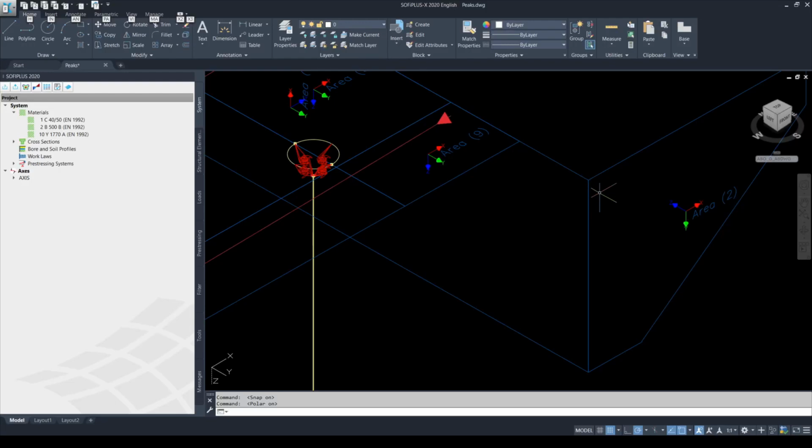I will just simply create a new material whose E modulus is going to be set to a quite small value, and I'm going to create an attribute area over the part of the wing wall that is failing in the design. In the properties of the attribute area, I'm going to set the new material with the small E modulus. This will allow the internal stresses to redistribute into other parts of the structure.